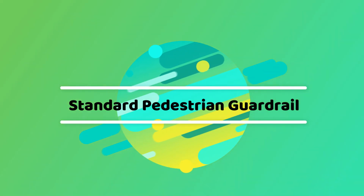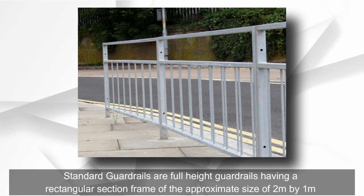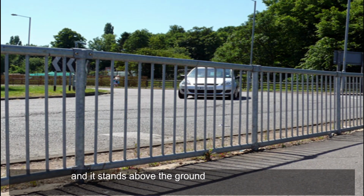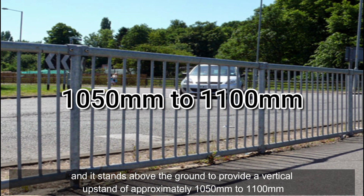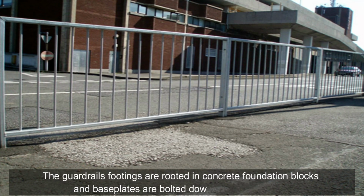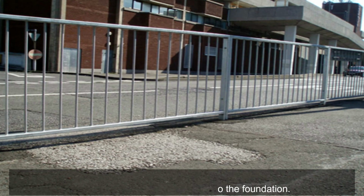Standard pedestrian guardrail. Standard guardrails are full-height guardrails having a rectangular section frame of the approximate size of 2 meters by 1 meter, and it stands above the ground to provide a vertical upstand of approximately 1,050 millimeters to 1,100 millimeters. The guardrail's footings are rooted in concrete foundation blocks and base plates are bolted down to the foundation.